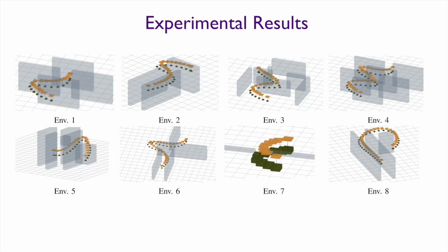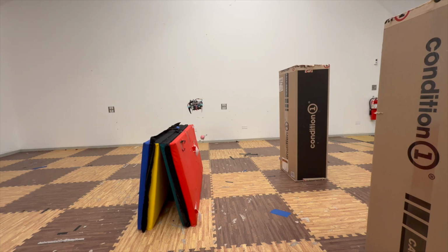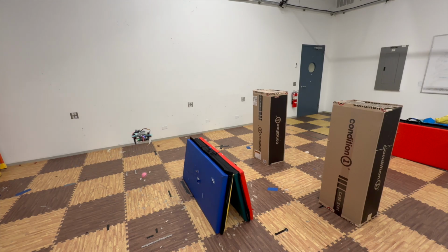We evaluated our method in 8 different test environments and produced faster trajectories than the baseline in each test case. We believe this boost in performance of our method stems from our non-conservative modeling choices that enable flight close to obstacles and the integration of smooth, differentiable polytopic constraints that allows the solver to converge to solutions even in difficult environments. We recreated a subset of these environments in the real world and validated that these trajectories can be tracked by a real quadrotor carrying a suspended payload.